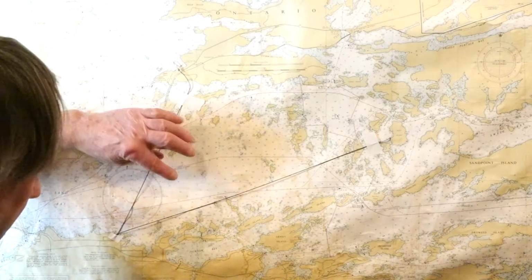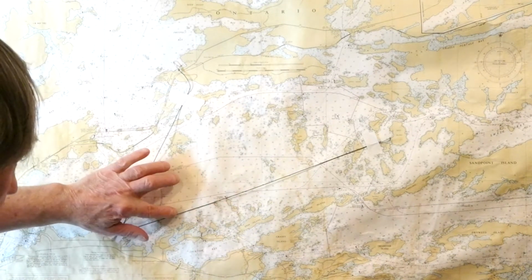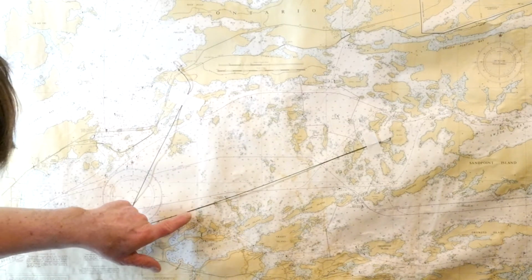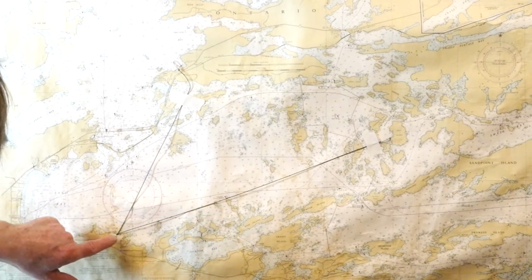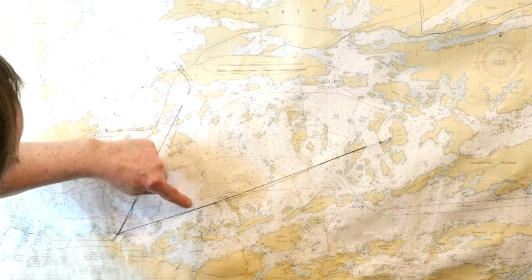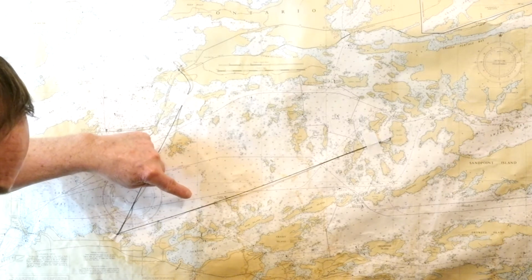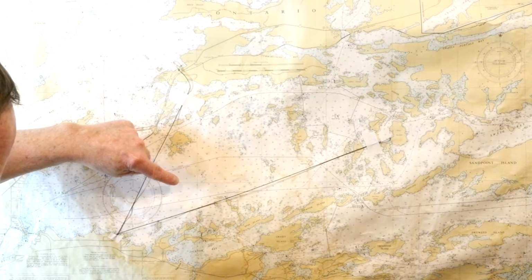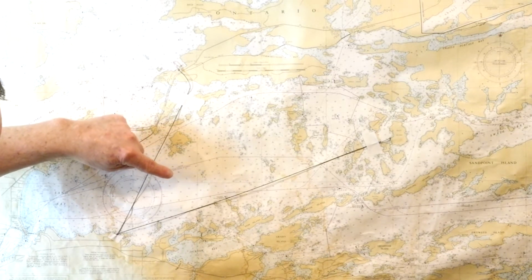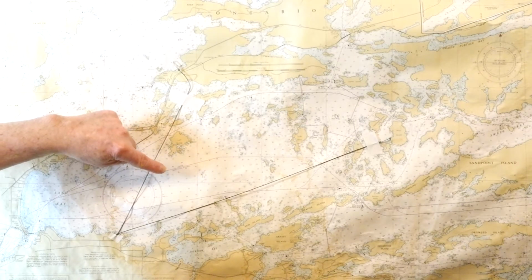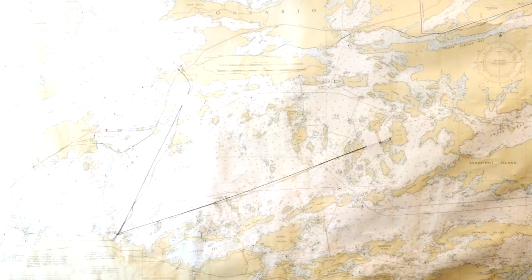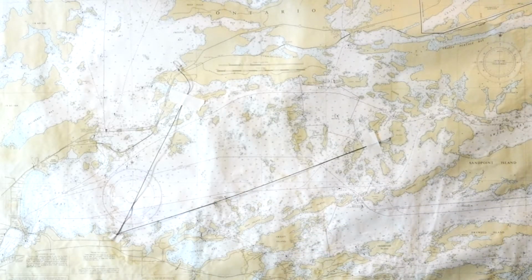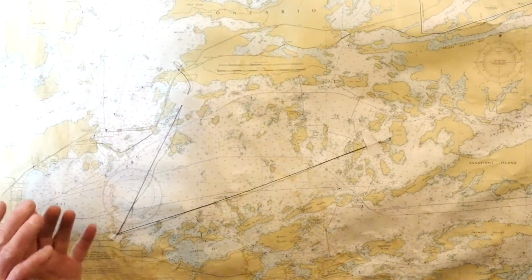Earlier today, I set up a marker pole halfway in between at the 1.36 mile mark from the reference point. The coordinates where this pole is set up is 48.62134 degrees north latitude by 93.27999 degrees west longitude. So that is the setup, and what we'll be doing is setting up targets on these